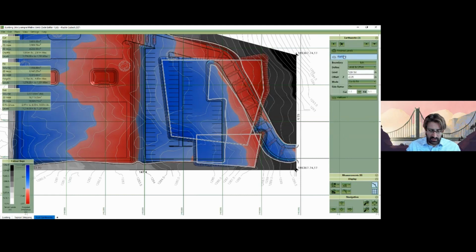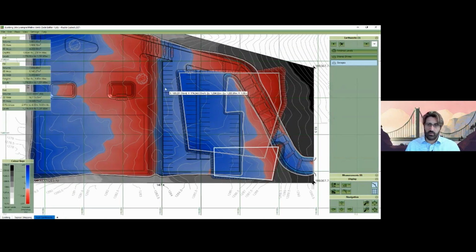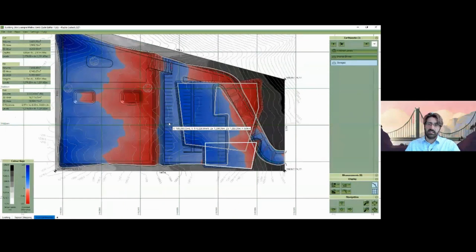I'll rename that too. So in the past, this would have just reported as one amount of earthworks. So you would have had to use the volume regions maybe to try and trace around each of the different areas. It looks kind of easy on this, that would work, but when it came to really big building sites, that's a lot of tracing. Apart from that, the volume region actually splits up the mesh. It kind of cuts the mesh into different chunks to do another calculation, which is computationally difficult. So you're quite likely for that to not be able to give you the full report, because at some point it might fail to break that down by volume.